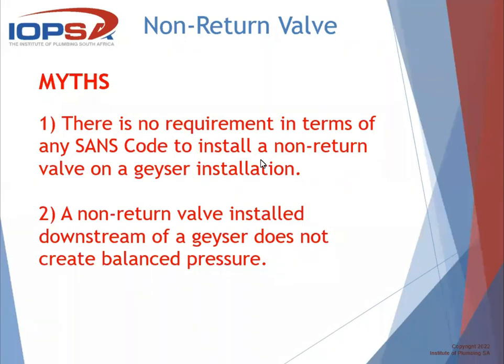But in situations where you've got a pump that is simply running 24/7, not only the electricity for the pump, but also the constant flow of hot water and heat loss through that loop, constant 24/7. And on top of that, if it's not lagged, then you're on a hiding to nothing. Yeah, and I think maybe important is to once again understand that the flap type is not to be used on a potable system. So, Bernardus, maybe you must just rethink your plan regarding that.